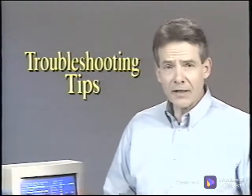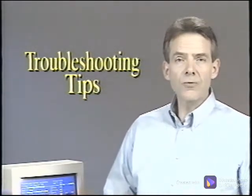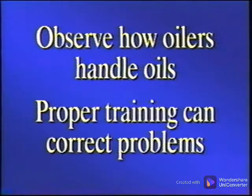As you implement your oil analysis program, there are a few things you should remember that will help your oil analysis program have immediate successes. First, if a machine failure occurs, thoroughly clean out all wear debris before refilling the system. If it is not cleaned out and flushed, the wear debris will quickly cause another failure. Observe how oilers handle the oil for the various applications. Many times the wrong oil was used because it was closest, and the oiler did not realize the severity of using a different oil. Proper training can help avoid this common problem.